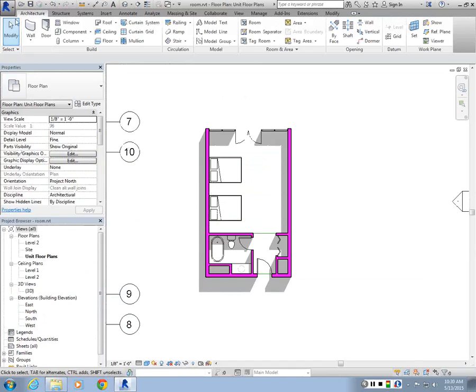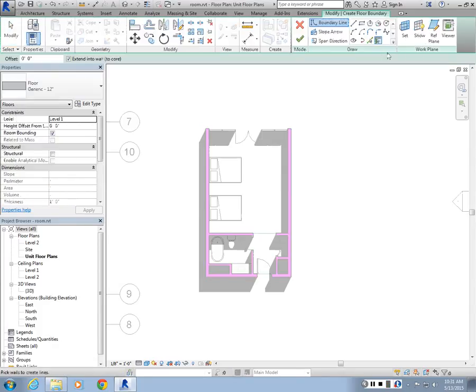Like any other Revit objects, floors are also objects themselves, so they're type specific. We have the floor tool here under Architecture, and these are sketch based objects. While walls work in the vertical dimension, so you can specify their thickness, it's the same thing for floors. You can specify the thickness, but you will sketch the outlines of them in plan view.